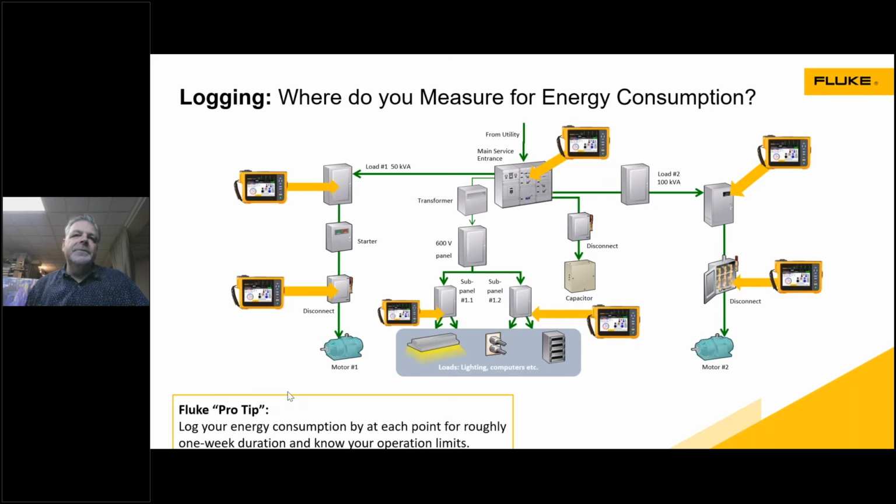I would like to add to this pro tip and suggest that you move it around on a frequency that makes sense, and you can start to log data and trend data. And rather than leaving it in a cabinet, I suggest you pull it out of the cabinet and put it to use for you. When I say cabinet, I mean a tool cabinet, but it can sit in your electrical distribution system and record data for you. Go back a week later and add that data file, maybe do a quick analysis to make sure it didn't change from the last time you made an analysis, and just continue to rotate it. All right.